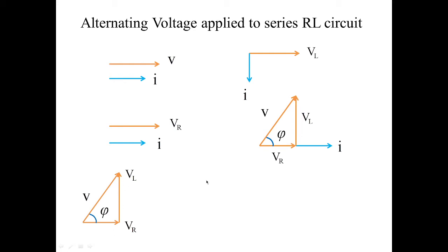If this is true, I can even construct the phasor diagram for resistance and inductive reactance with impedance at an angle phi. So this becomes the impedance triangle of RL circuit. When you take the trigonometry relations, you get cos phi is equal to R by Z. So this is how you represent the phasor relationship for RL circuit.